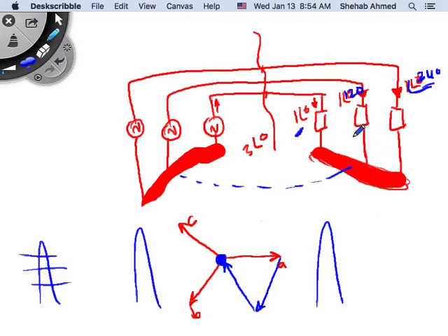So this is something we cannot control at the distribution level. In this building, for example, 3-phase comes in to the building. Then the engineers that designed the electrical system of the building took 1 phase. Here in this room, we are using one of the phases, right? All the loads here are single phase. So the lighting is single phase, the projector is single phase, these are all single phase outlets, etc.